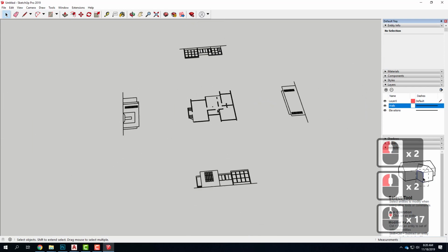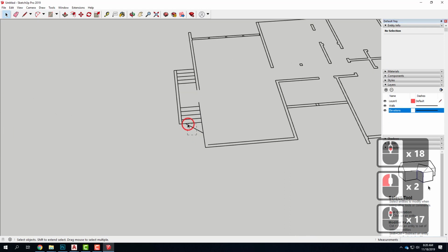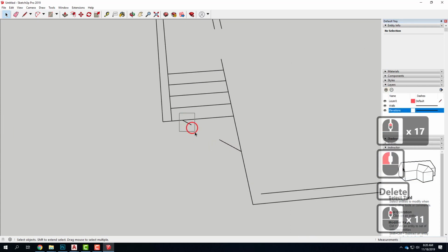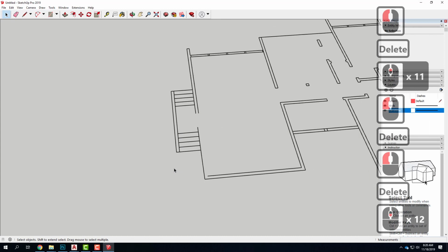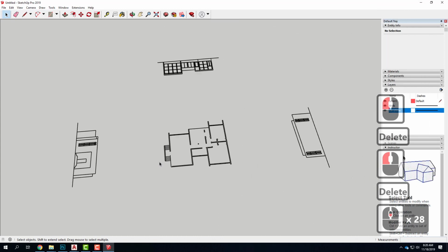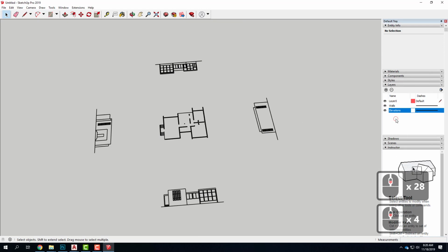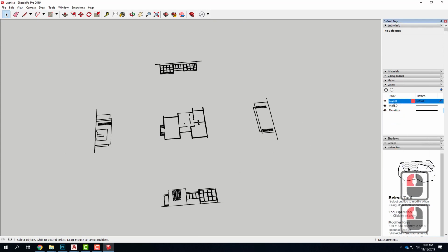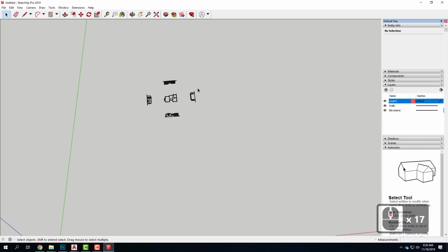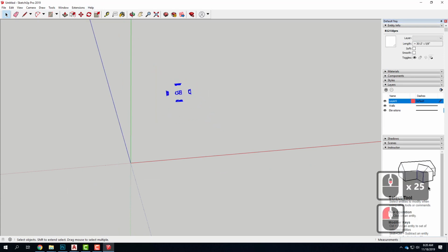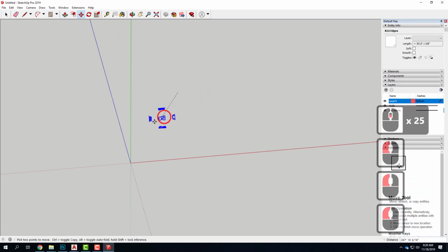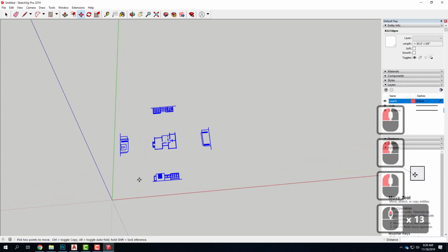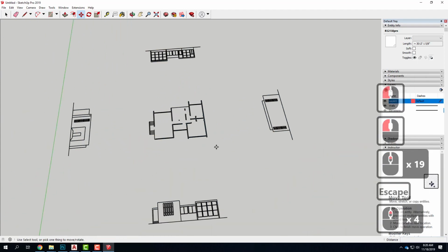That's good. And the elevations. That's good as well. Oop, there's a little extra piece. So I'm really taking care to make sure that I've gotten rid of almost everything in my drawing. Like that. All right, that looks pretty good. So I have walls and I have elevations. Layer 0, by the way, is the default SketchUp layer. So now that I have these pared down, it may be a little bit easier if I took them and I moved them. I'll use the move tool here, just closer to the origin. It'll be less distortion as I'm working.